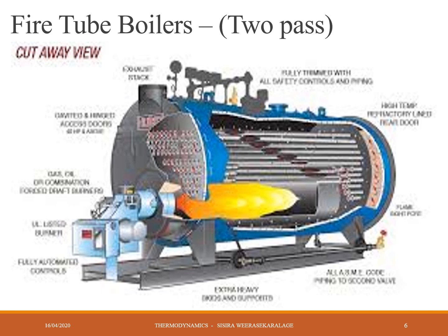Two-pass boiler means the yellow flue gas goes towards the end back plate side, and from the back plate side again it passes towards the forward side through tubes and comes to the front and leaves through the chimney. Chimney is not fitted here, but it can leave through the chimney. So this is two, because forward path and backward path, only two passes, number of passes. Okay, it is clear.